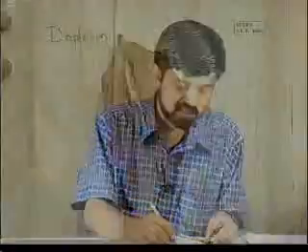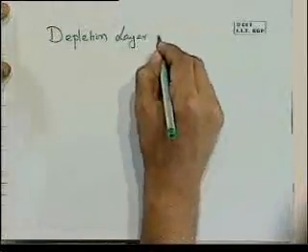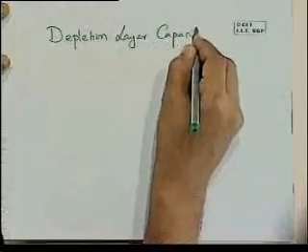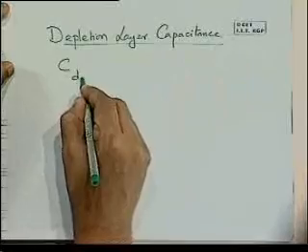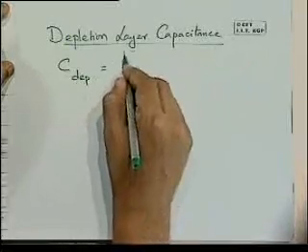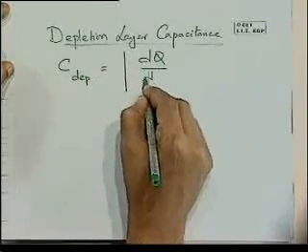You've got positive, you've got negative charges. You've got a dipole, capacitance, right? It's charge storage, fixed charge stored there. It's capacitance. So we talk in terms of depletion layer capacitance, where capacitance of the depletion layer is defined as dQ by dV.